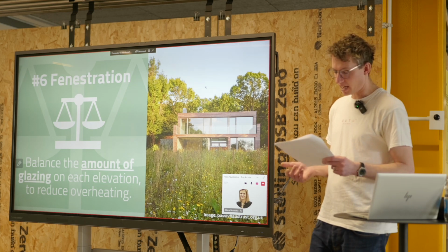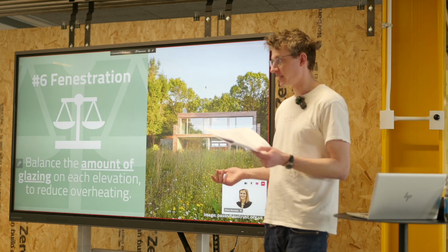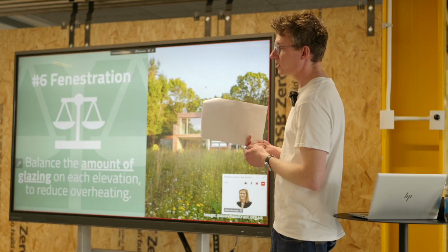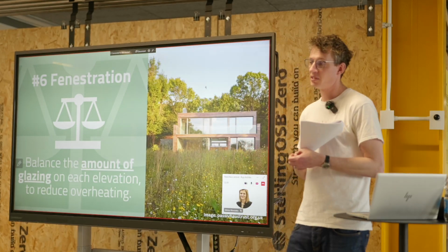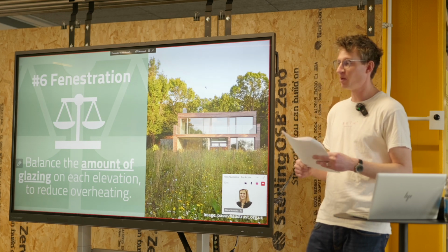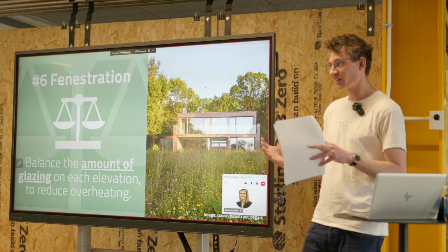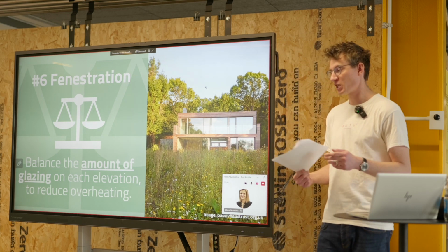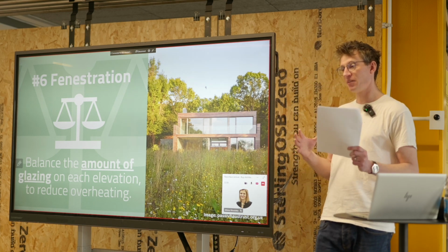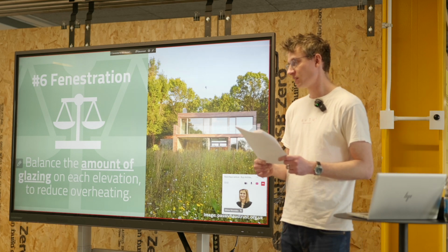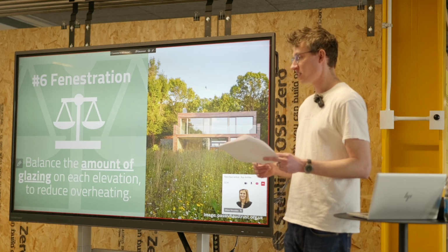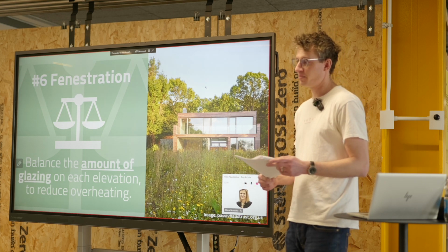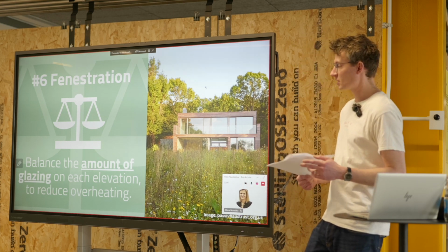As well as supplying natural light, the windows should also be considered for natural ventilation. What you'll often find in buildings these days, and you might have come across this in the news, is that there's overheating issues because buildings obviously become more insulated. There's often more glass as well, and an important part of the Passive House planning package is to analyse the amount of overheating, which is a huge consideration. As you can imagine, on a hot summer day, you don't want the building to be so uncomfortable that it becomes unsuccessful, basically.